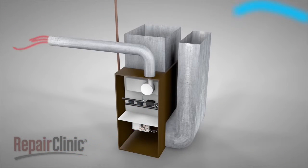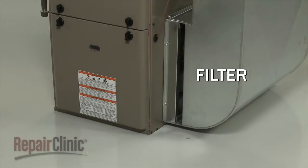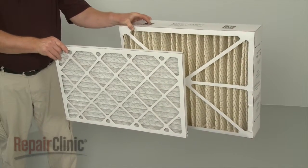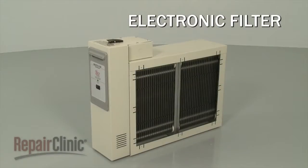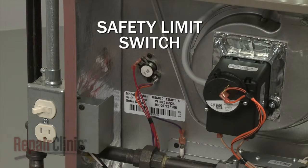The most important factor in efficient furnace operation is air circulation. To ensure proper air circulation, the furnace filter should be checked monthly and replaced as needed. There are several types of filters available and range from 1 to 5 inches thick. The filter can be installed into the slot in the return or in an air cleaner. Some homes will have an electronic air filter, which is powered by the furnace control board when the circulation blower fan turns on.